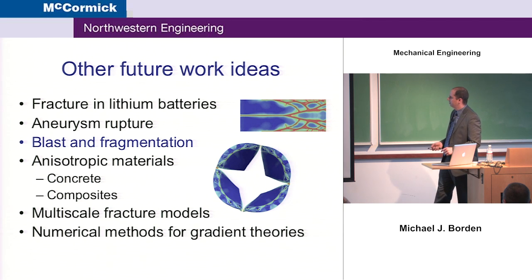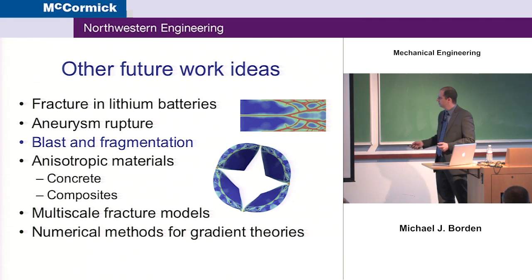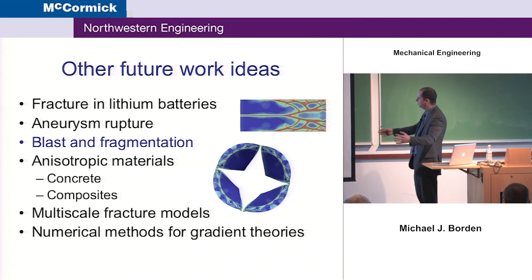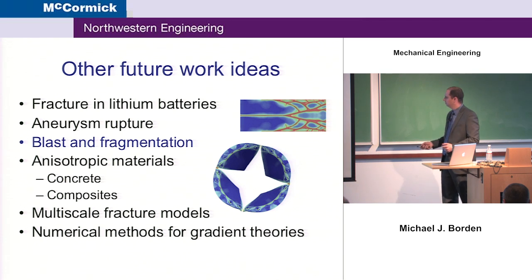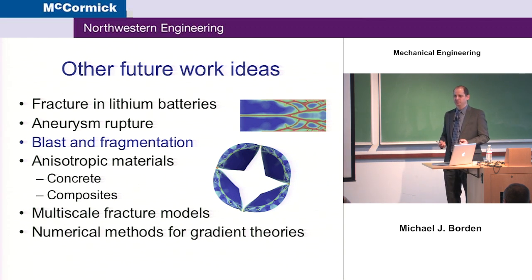Another thing is blast and fragmentation. So we see that we can do these complex crack topologies. We can do large deformation models with our phase field models. I should point out again that this is all done on the original mesh. You don't see the elements here, but if I drew the elements, there's one element through that crack that's being stretched out, and we can handle that effectively. There's some other work that we'd have to do. We'd have to develop some more fluid structure interaction type formulations to get this correct.